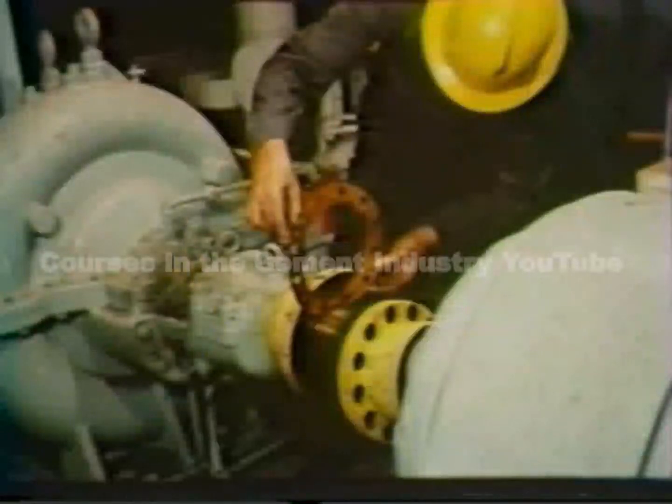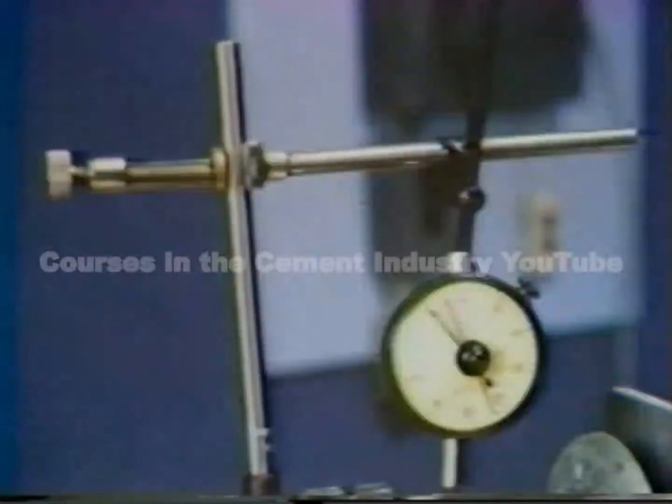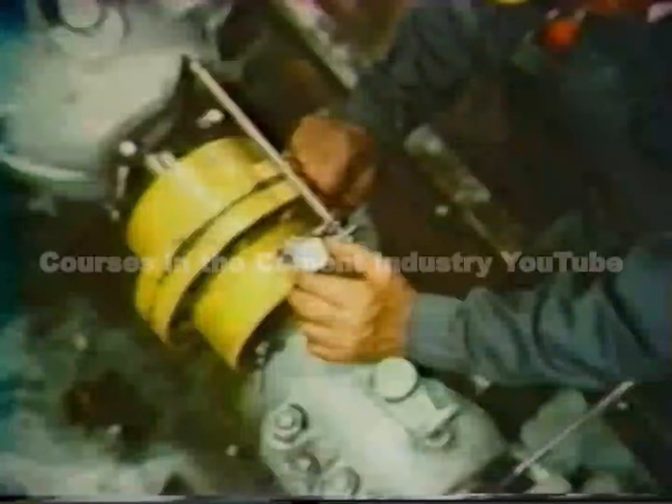Things like routine coupling maintenance and rough alignment using a feeler gauge and straight edge have already been done. It has also been verified that both shafts and couplings are round by using standard run-out procedures. Now you're ready to get started on the final alignment using dial indicators.